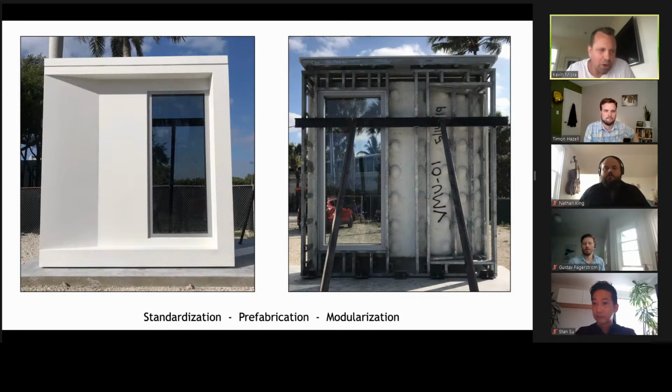COVID itself has been a disruptor, because the challenge on job sites today is the risk of going into the building and going on to the hoist to get up to the building. Our approach has always been to do GFRC as a curtain wall, so we'd be installing from the inside. But from a risk standpoint, that imposes new risks to us because of COVID. So we're evaluating going back to exterior mobilization of buildings and doing the erection of the facade from the outside.